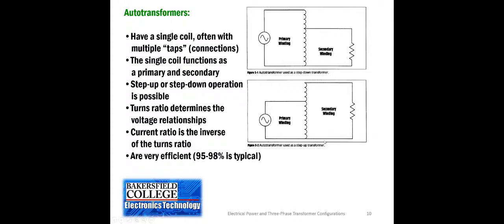In a Y configuration, one of those center connections is electrically common. So in the Y we don't have isolation, where one side of each of the coils is connected. Oftentimes it's very beneficial in a Y configuration to connect the neutral to that common connection. The motors that we use in our lab are all Y connected. We had a lab where we used a delta configuration, and the neutral, which is grounded at some point, created a higher voltage into the motor, and that means that the other side of the circuit was also the load side of the circuit for a very short amount of time.